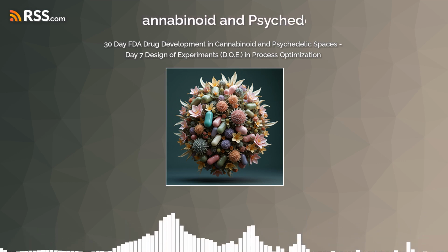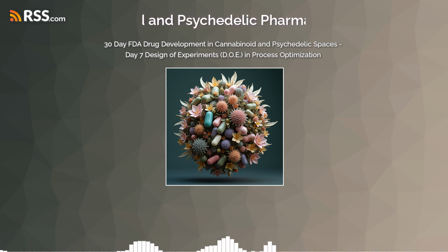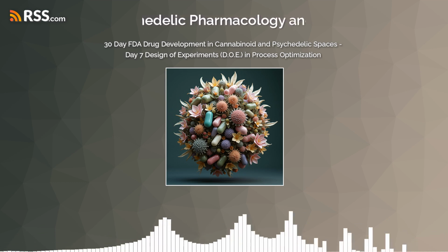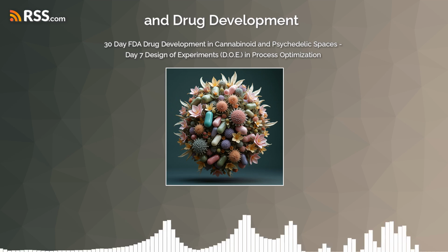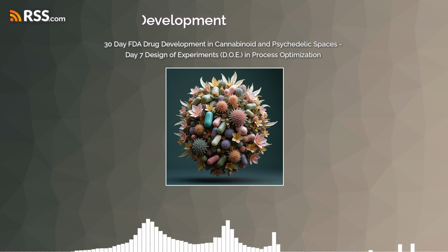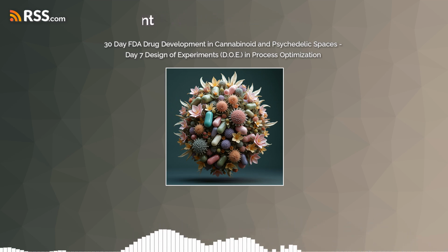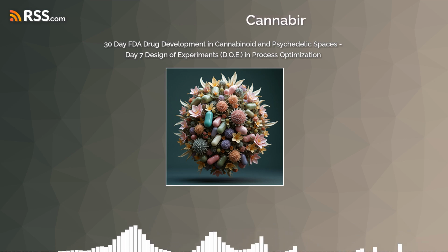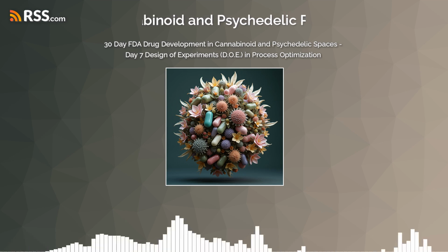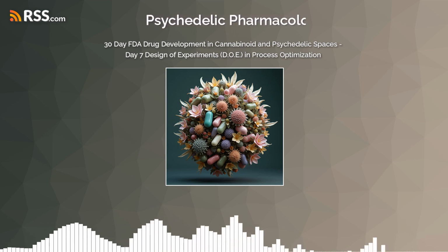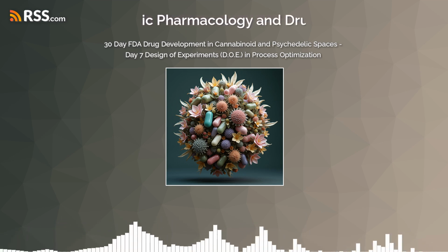Exactly. And DOE provides a structured way to explore those potential risks. So by systematically varying the process parameters, we can observe how those changes affect not only the desired product, but also the potential formation of impurities or degradation products. So it's like running a stress test on the process, pushing it to its limits to see where those vulnerabilities might lie. That's a great analogy.